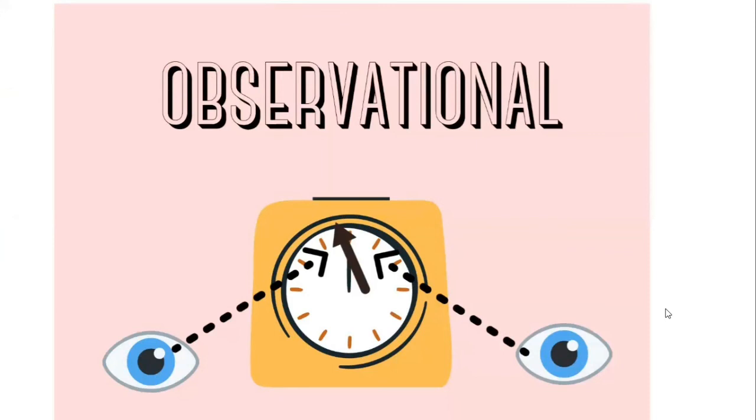Let's say you're taking a value from a voltmeter. You're standing on the right side of your voltmeter and your friend is standing on the left side of your voltmeter. If you see from the right side, you will be seeing a value. But if you see from the left side, your friend could see a different value. Maybe it could vary only by a small point, but still the value will differ. So what we have to do is stand straight to the machine to measure the instrument.